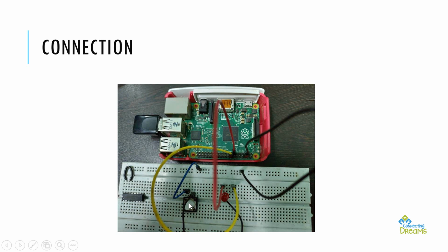So the idea is, when the switch is pressed, at that time this ground signal would be reaching the negative terminal of the LED. At that time, this particular 16th pin, which is already high, will make this LED go on because the circuit completes. Whereas when the switch is not pressed, this ground will not reach the negative pin. So even though the supply is available for the 16th number pin, this LED will not be on.